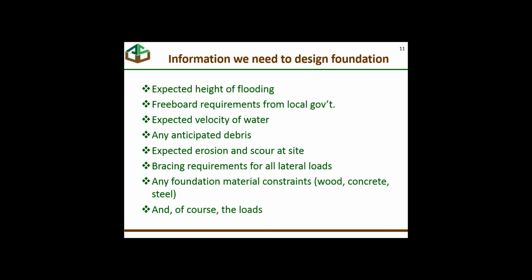If the water is carrying debris and is likely to strike a building, then we need to know what that anticipated debris is. And when the water moves past an object, again a building, a pile, or a column, it's going to create scour at that particular element, and over the course of a wide beach or a wide floodplain can cause erosion in addition to that.